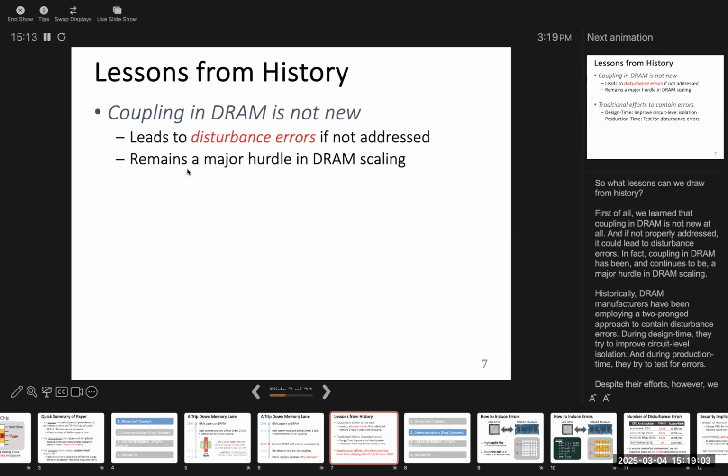Let's say the technology size is 3 nanometer, which is too small, right? 3 nanometer means that the width of the channel of the transistor is only 3 nanometer. Which basically means you are packing too many transistors very close to each other. As a result, the electric or magnetic field generated by the current flowing through one transistor affects the other transistors in the neighborhood as well.